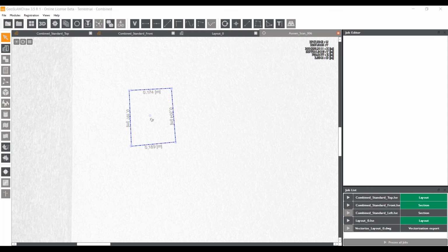Okay, next question. You show this case comparing GeoSLAM to a stationary scanner. As I get it, you scanned that building at once and I may have missed it, but what was the maximum deviation of error? Or maybe you can say, what is the maximum suggested length of scanning with Horizon to stay below 5 centimeter error on the full dimension?